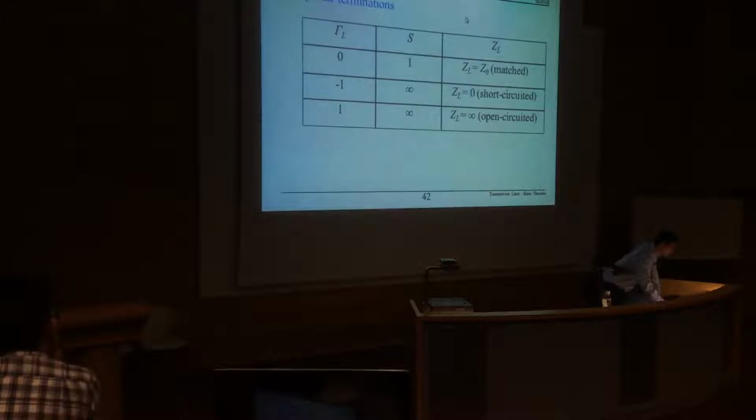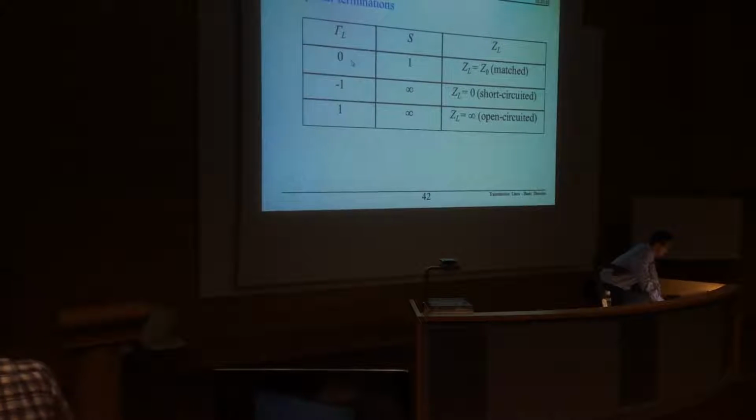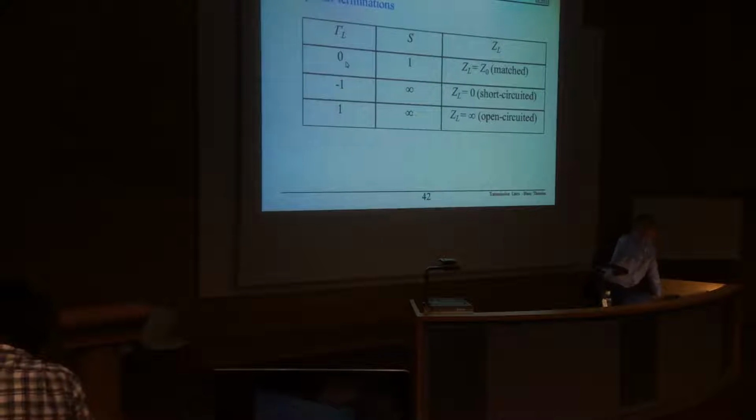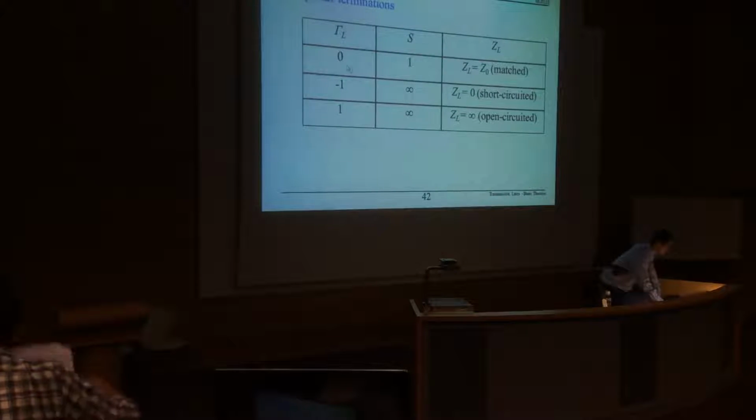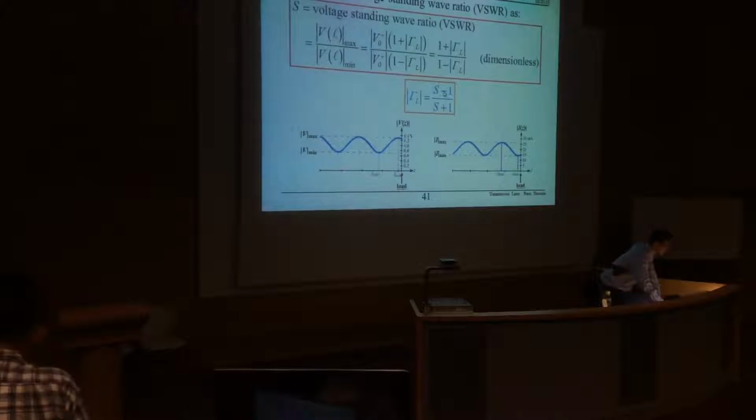So for some special cases, previously I guess we have mentioned, for instance, a matched load. A matched load means the reflection coefficient is 0. If the reflection coefficient is 0, then from this equation the standing wave ratio is 1.